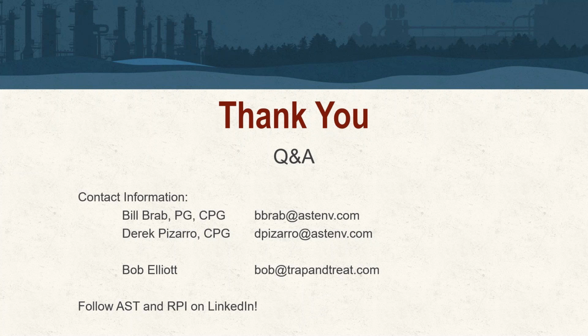That site there, I think our estimates for ROI at most of the intervals were 50 to 60 feet between boreholes. And we know at that site that we got almost 130 feet because it started to weep out of that contact zone along a road cut there. So we actually had someone monitor that because we didn't want to continue to propagate product out of that zone.